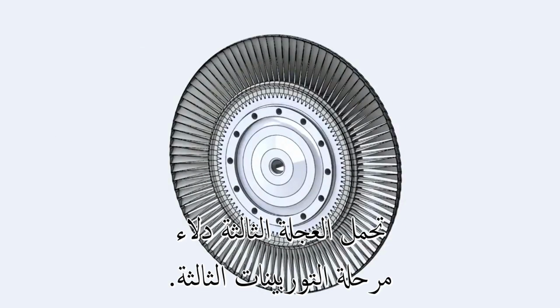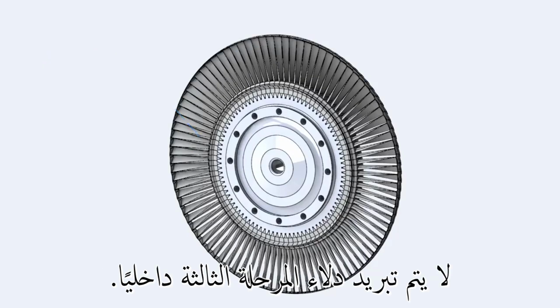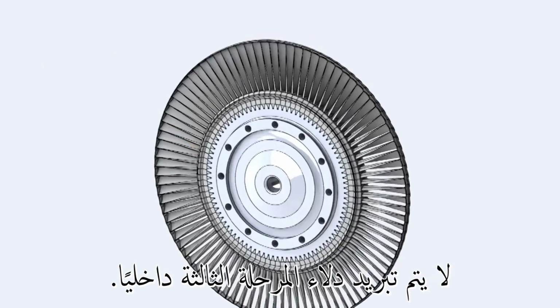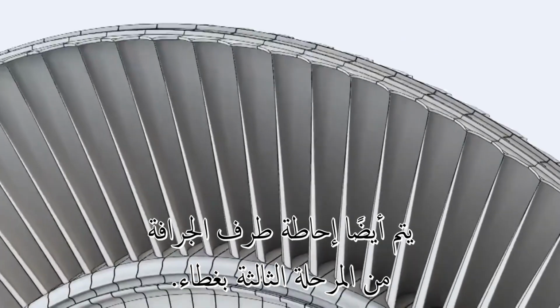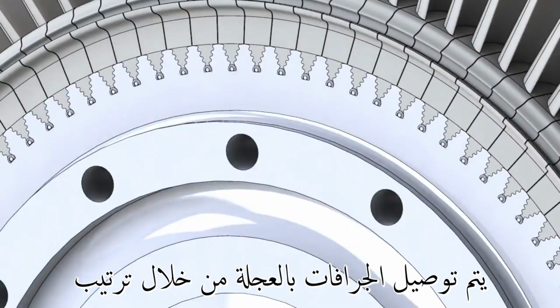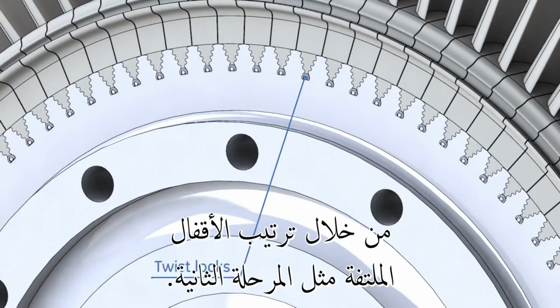The third wheel carries the buckets of the third turbine stage. 92 buckets are also installed on the third wheel. Third stage buckets are not internally cooled. The third stage bucket tip is also enclosed by a shroud. Buckets are attached to the wheel by the dovetail arrangement and held in the axial direction by a twist locks arrangement